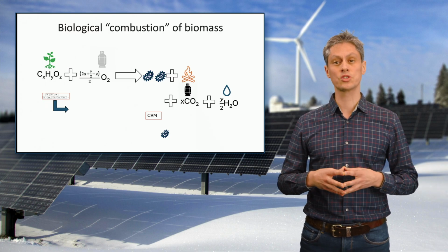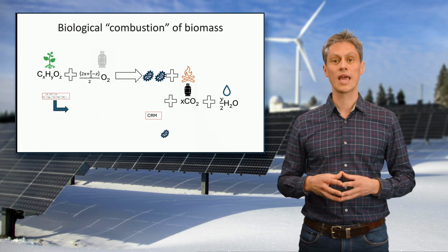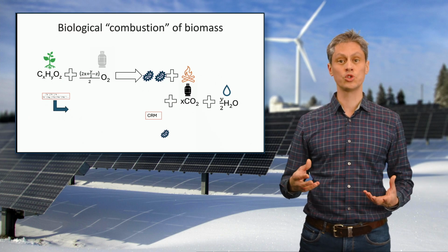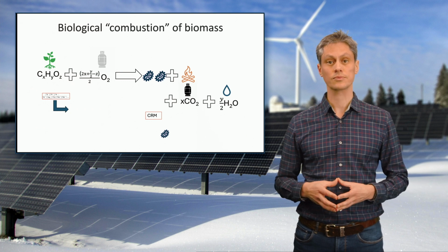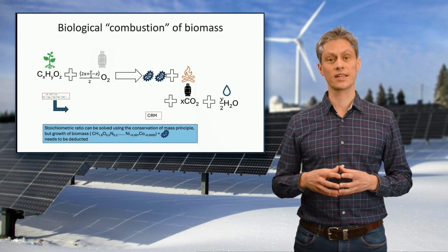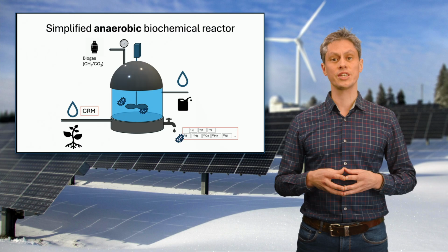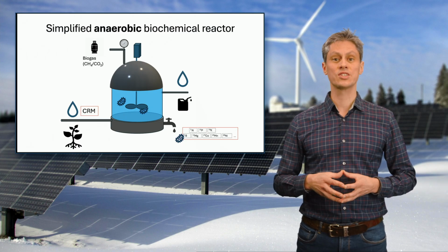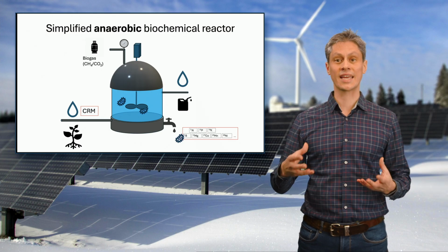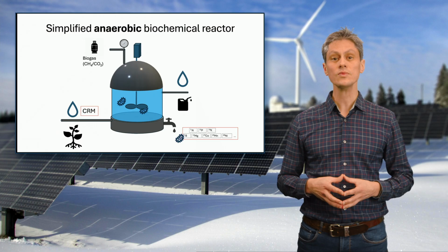It should be noted that stoichiometrically the mass balance is similar to the thermochemical process. However, the elements contained in the biomass should be deduced from the product side. By ensuring oxygen cannot enter in the bioreactor, the biochemical energy contained in the organic feedstock is now more efficiently transferred to the reduced end product, a cleaner gaseous fuel of CH4 and CO2.